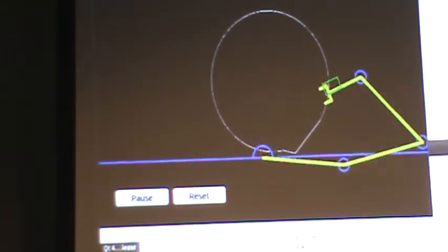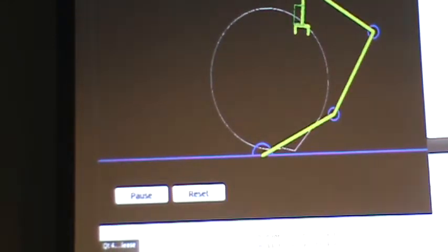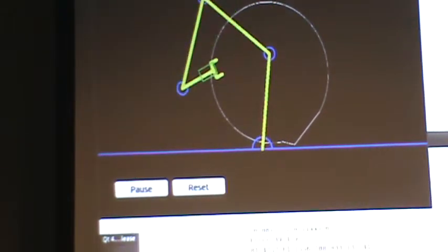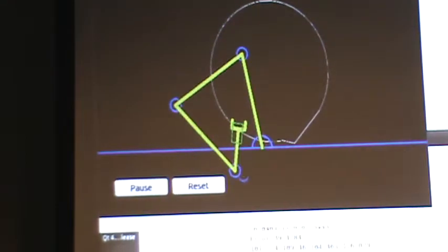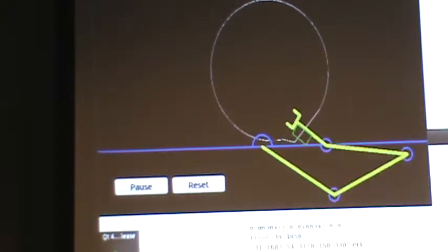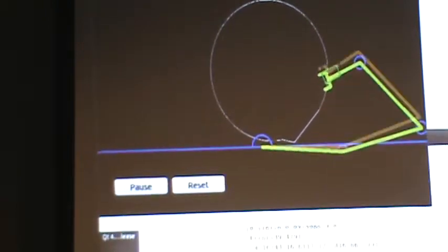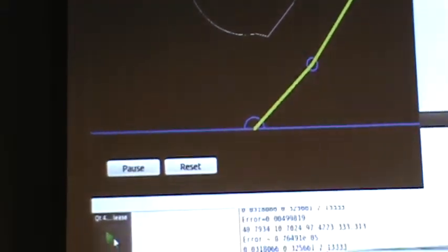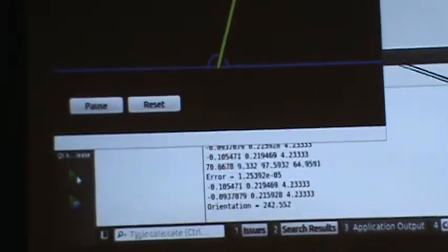The problem is that when you have joint limits, the solution you get may not be perfect. In order to search for the perfect one, you need to move one angle, let it float, like become a free variable, and then adjust it. So this is actually doing some optimization here. You see it's doing all this calculation, trying to optimize the errors. The error criteria I'm using